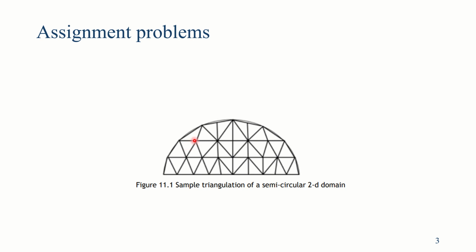But here, if I move in this direction I get this neighbor, and if I go from here to here, I cannot identify the exact neighbors from the current cell, that is, the cell of my interest. I am not able to track the neighboring cell list, so I need to keep track of a neighbor cell list. So I can say that it is an unstructured grid.